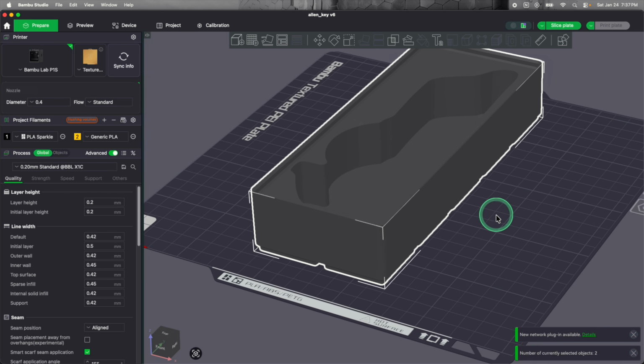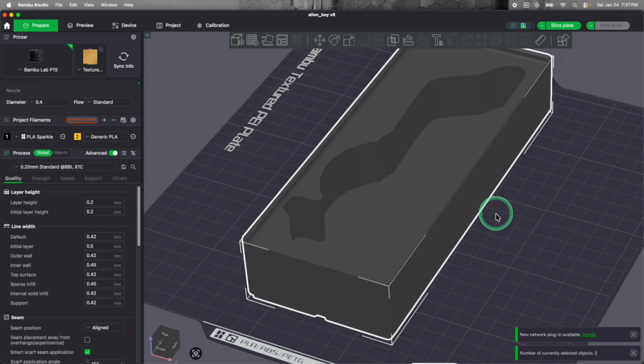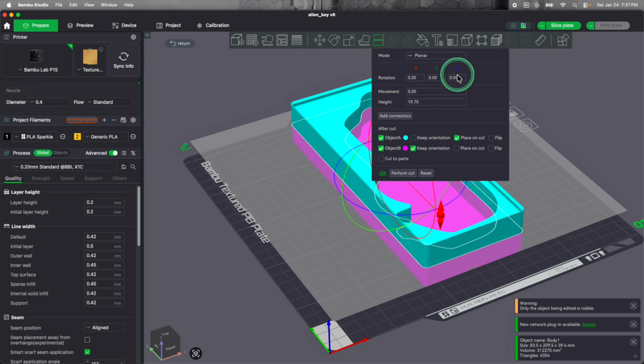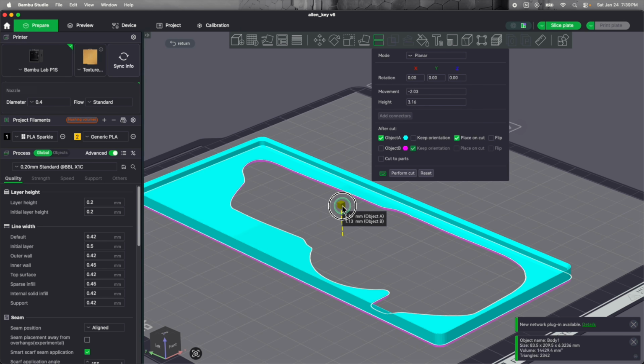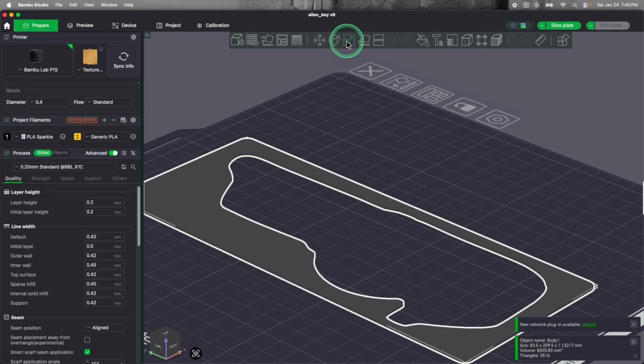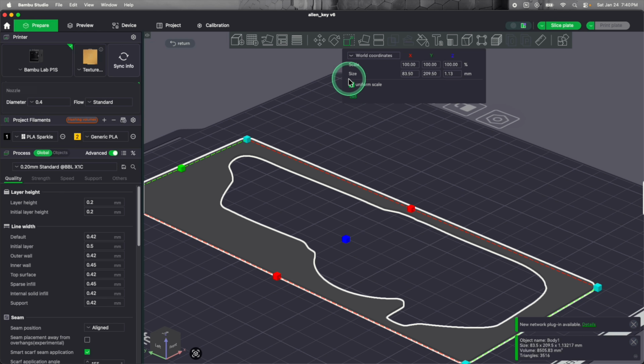To do this, simply bring your part file into your slicing software, use the cutting tool in the toolbar to slice the part at a section that approximates your closest fit, which for me was anywhere along the Allen key cutout in the vertical direction. Then for an added bonus, you can remove as much material as you'd like by repeating your cut to size it down, or you can go to your scaling tool, disable uniform scaling, then set your Z height as thin as you'd like to print out a simple silhouette of the tool.